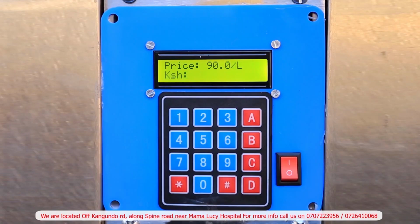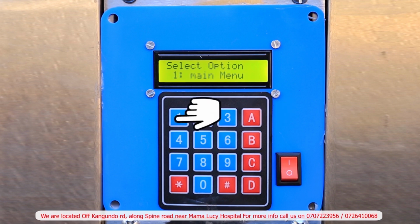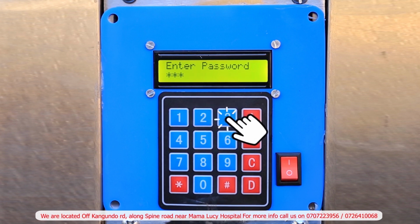To go to the main menu for the various settings the PLC has, you press the A key. In this case, you press option number 1. You will be required to key in an administration password, which we have set at 1234, but please note it is changeable by you, the operator of the machine. So when you press number 1, you key in the password and then press A to confirm or enter that password and unlock the various settings.